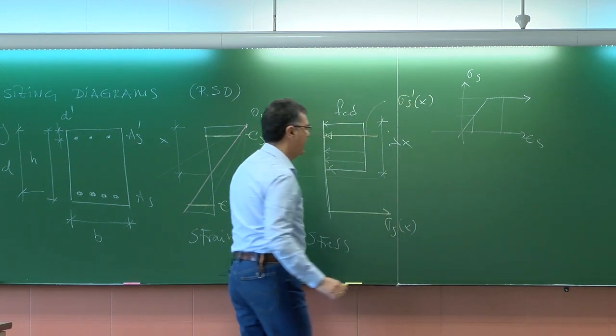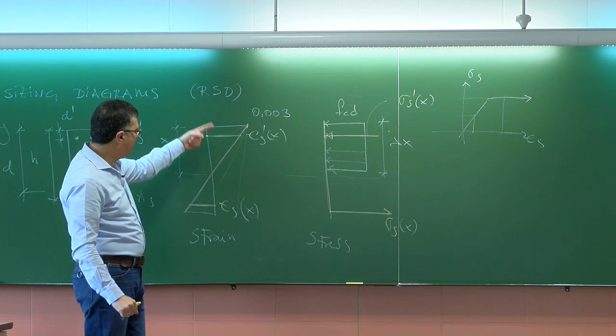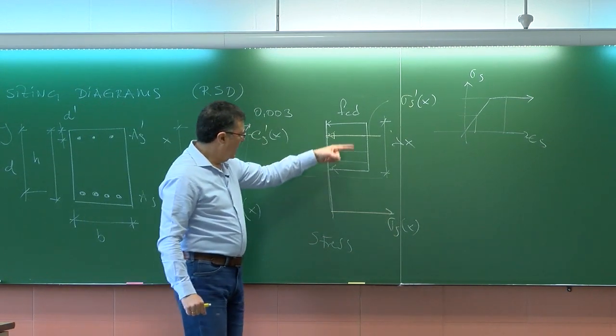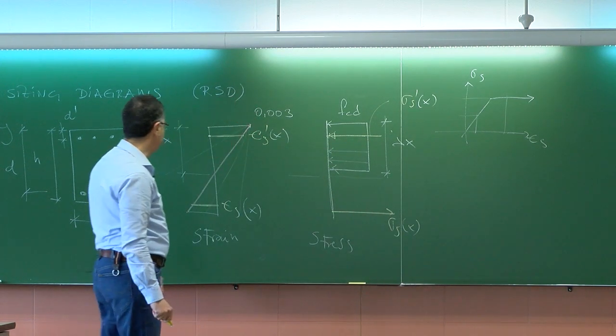Once I know x, I know the strain distribution, I know epsilon S and S prime, I know sigma S and sigma S prime. Perfect.